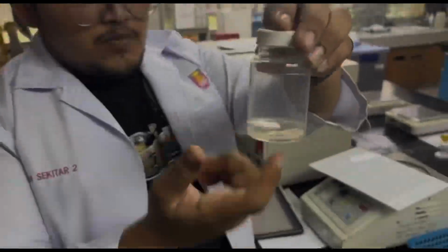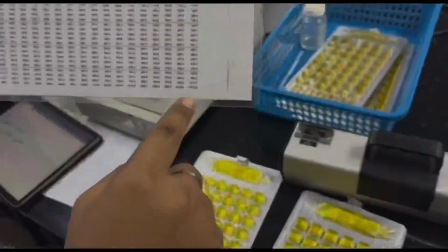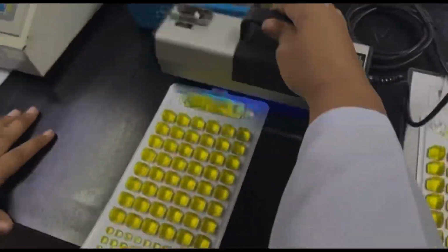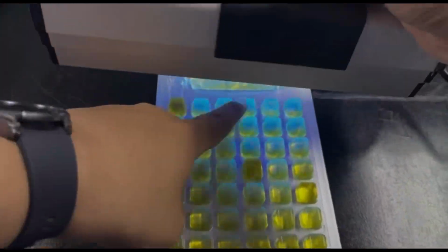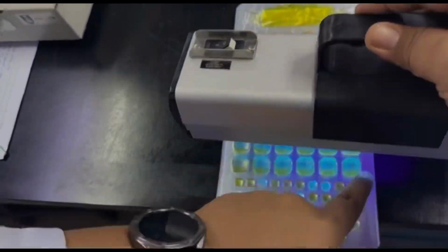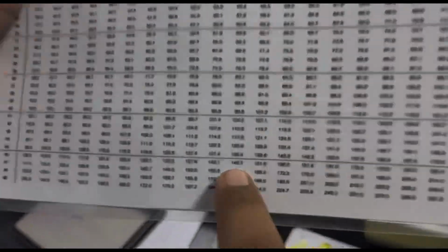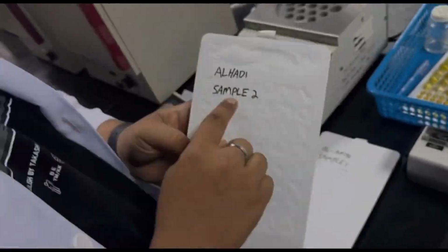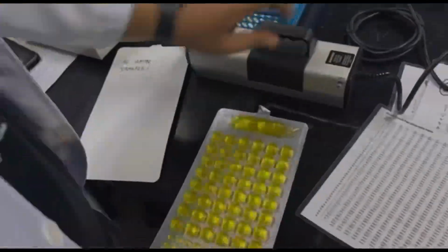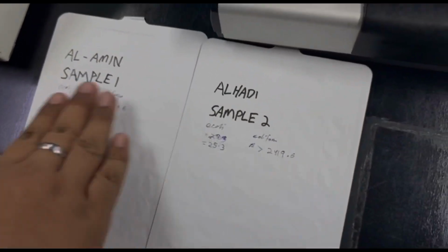After 24 hours, the E. coli sample tray was taken out. The presence of coliform is verified by comparing the yellowness of the sample in the E. coli sample tray with the standard coliform sample. Check the presence of E. coli by using a UV light. The number of luminous squares under the UV light was counted and the E. coli data was taken by referring the number of boxes to the respective value in the E. coli MPN table.